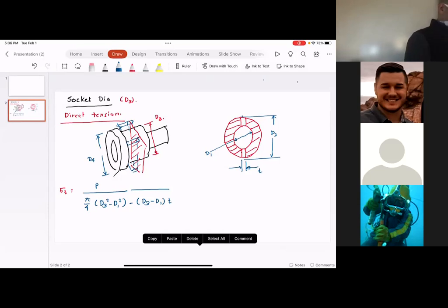So yeah, basically D4 is the diameter of the collar and D3 is the diameter of the socket. Yeah, in the recording about the cotter, it used D3 for the bending, but you used D4, so which should we use? Oh, actually, I don't remember what I used in the recording. As long as you understand the failures, that's totally fine. And then also the length of the cotter and the width, it says to use 4 times the rod diameter, which is what I used when I did mine. That's totally fine. But 4 times the rod diameter would approximately be D4, that's about 10 to 15 millimeters. Okay. Because that is how the proportion came about.